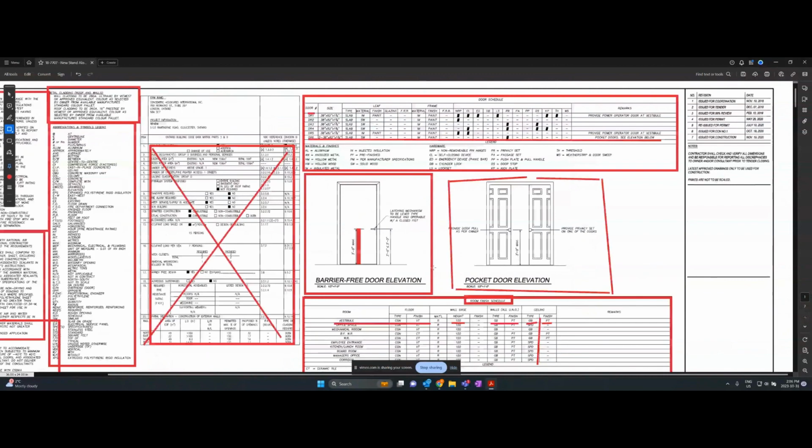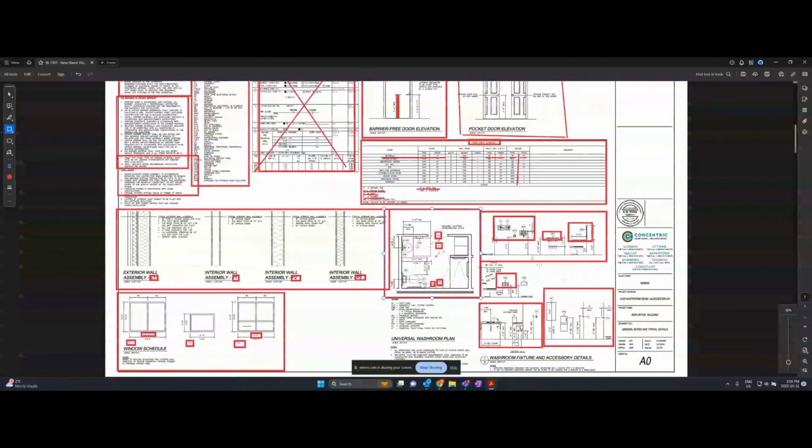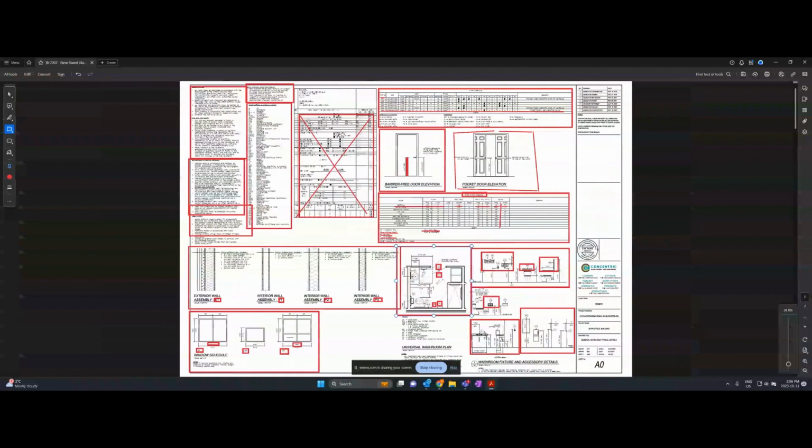So this was somewhat of a long video on this drawing. It is an extremely important drawing as it has so many different specifications and little notes and everything on it. Most of the time, you'll have one drawing that will show exterior wall assemblies, and then you'll have another drawing that shows the room finish schedule, door hardware schedule, window schedule on one. Not kind of convoluted like this, but at least this drawing kind of shows us everything.